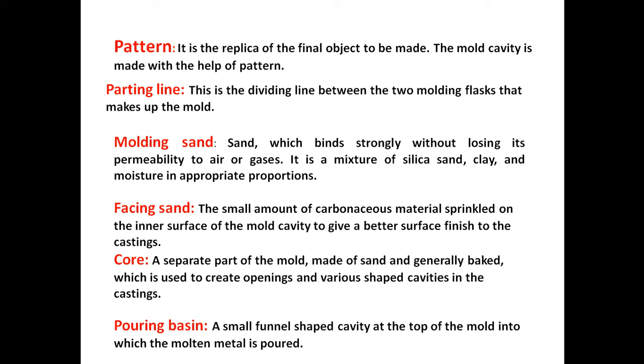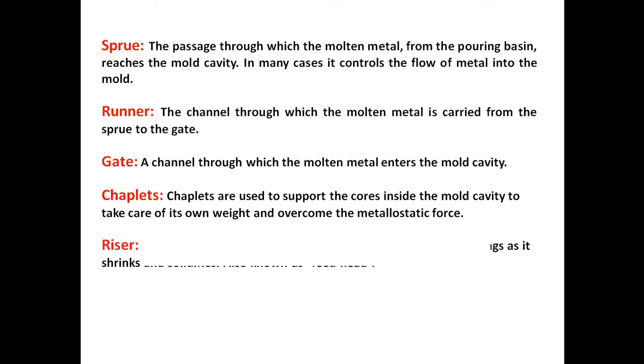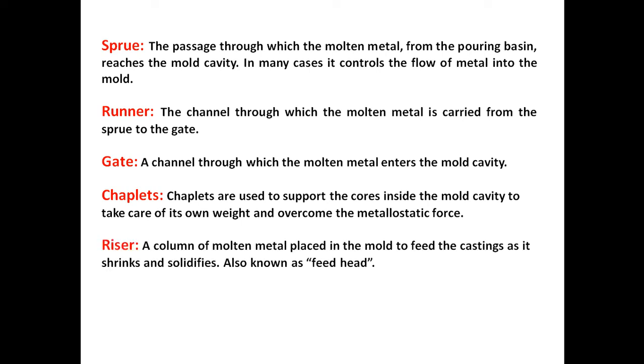Core, I told you, is to form a hollow portion. Pouring basin, we already saw this. Sprue, runner, gate, chaplet. Chaplet is something which supports the cores. See, chaplet is something which supports the core. Suppose a core has to be placed. Now this core has to be supported with something, and that supporting component is known as a chaplet. Riser is already discussed. Vent is a hole.